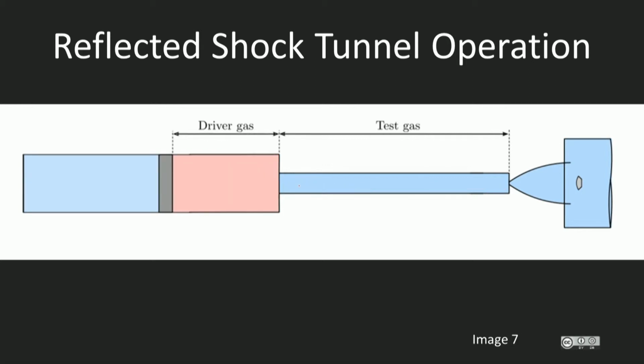The piston rapidly accelerates down the 25-metre driver tube due to the high pressure force applied to its rear face. As it travels down the tube, it compresses the helium-argon driver gas in front of it, simultaneously heating it. For most of the piston stroke, the pressure force behind the piston is much higher than the pressure force ahead of it. So the piston continues to accelerate and compressively heats the driver gas at the same time.